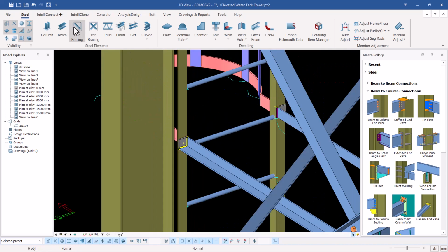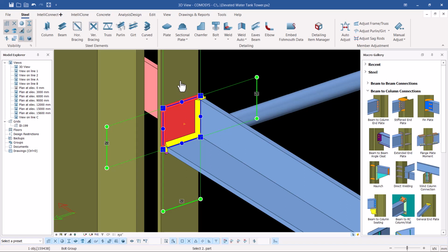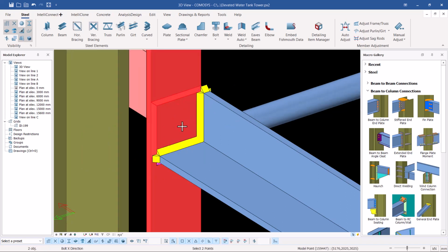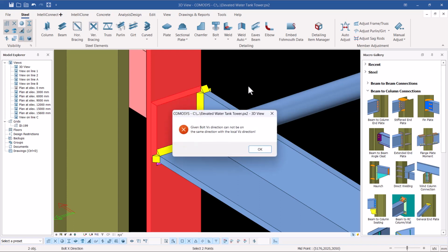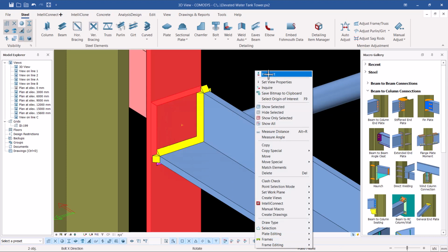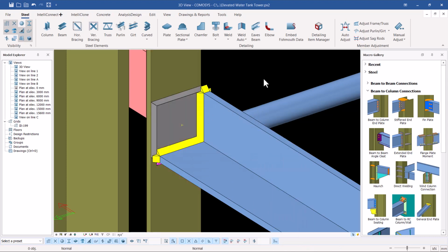The tool that will help us in creating the bolts, we'll come to bolt here, pick up the bolt, then pick this member and that member. Once I've done so, right click and snap on that point, snap on that point, and maybe snap on the next relative point, and you'll create a bolt. But if you take a look at the screen here, our XYZ direction is wrong, so we have to reorient our XYZ plane.